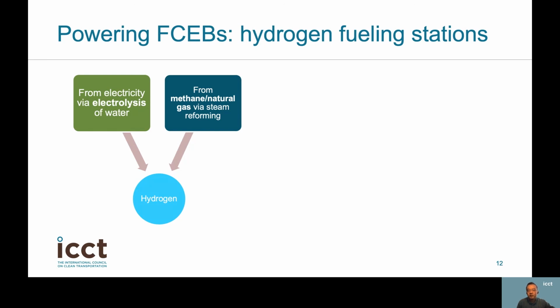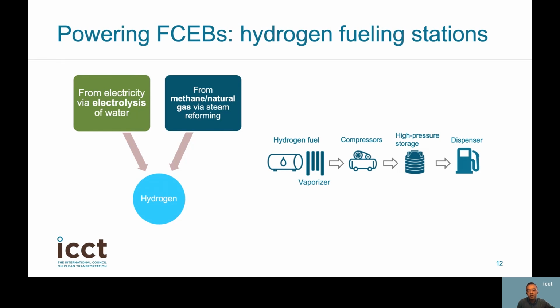The term green hydrogen refers to hydrogen produced from water electrolysis using renewable power, and conversely, steam methane reforming is referred to as blue hydrogen. If the power required for electrolysis is 100% renewable, this can theoretically eliminate all greenhouse gas emissions. Production of hydrogen can either take place on-site where refueling takes place, or from a centralized supplier, which then delivers the hydrogen fuel. Hydrogen can be produced in either gaseous or liquid form.